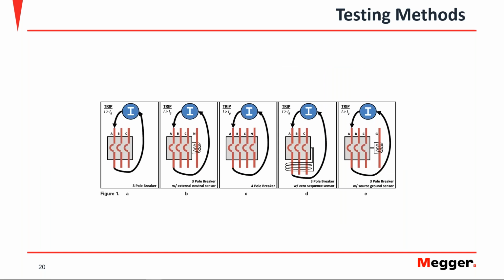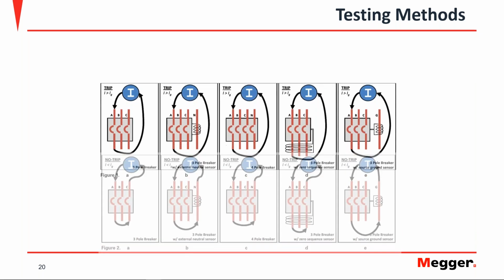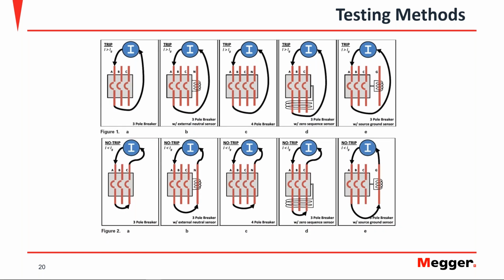Now for connections, right? If you have been performing not only ground fault protection testing on circuit breakers, but all the others, if you're testing just the breaking capabilities of the breaker for short circuit or for your long time or short time elements, you'll find the connections pretty familiar, right? You need, of course, a current source, and you can inject the current on each one of the phases to perform the measurements again phase by phase in the case of a three-phase breaker.